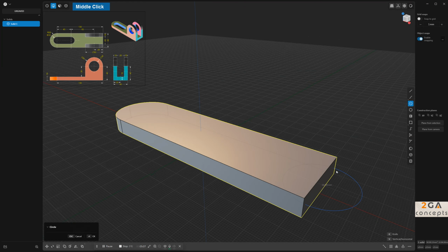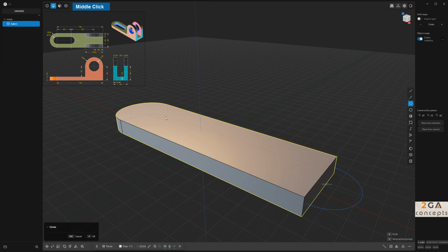it's not a problem really, because we're going to punch through the whole body with this shape. But if you want it on the face, no problem, you go on that, right? And we're going to input the radius, so it's a radius of 10.